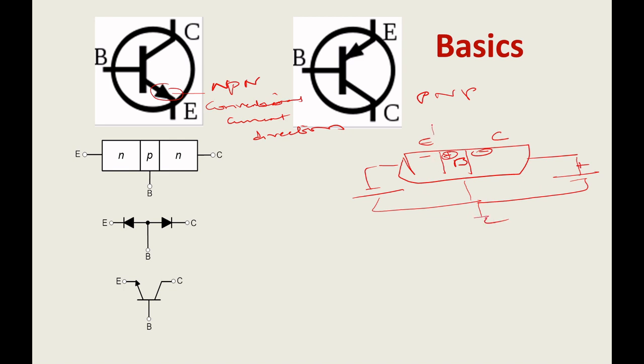So this is junction 1. If I go into it, it will become a device topic, so I'm not going more into it; I hope you remember. J1 is your emitter-base and J2 is your collector-base. This should always be forward biased, this should always be reverse biased. When you do the biasing, see students, the electrons will move like this, right? The electron will be moving like that. This is the electron current actually.